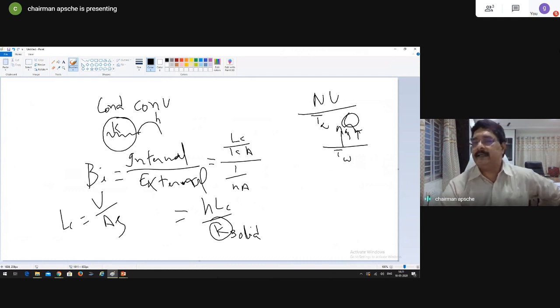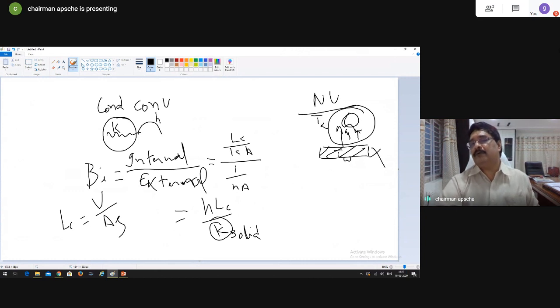So what do I say? The heat transfer from solid to fluid is a combination, an addition, of pure convection, that is, the bulk motion of the molecules, a molecule going to the hot spot, taking the heat and going back, and also molecular interactions within the fluid itself. I'm talking about this zone. I'm not talking about the solid at all. I'm talking about the fluid.